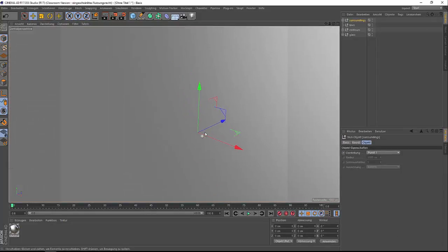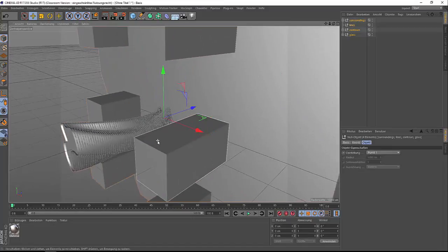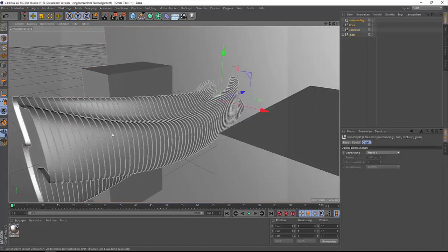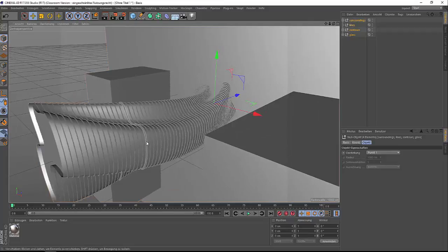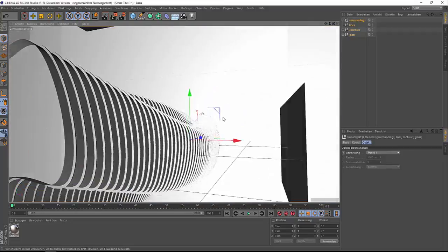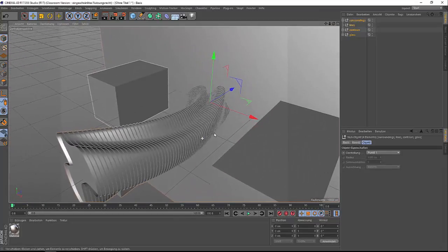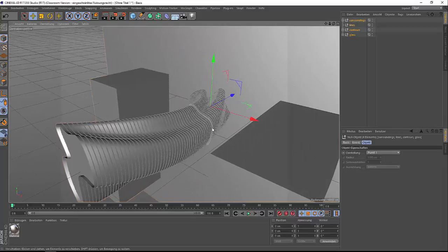Now, the problem that you're gonna have with this is that probably the sides of the model are going to come out not matching the sides of your viewport, and this is a normal problem. Also, you're gonna see that your project is using a different type of coordinates, and this is due to the fact that basically Rhino and Cinema use two different types of coordinates.